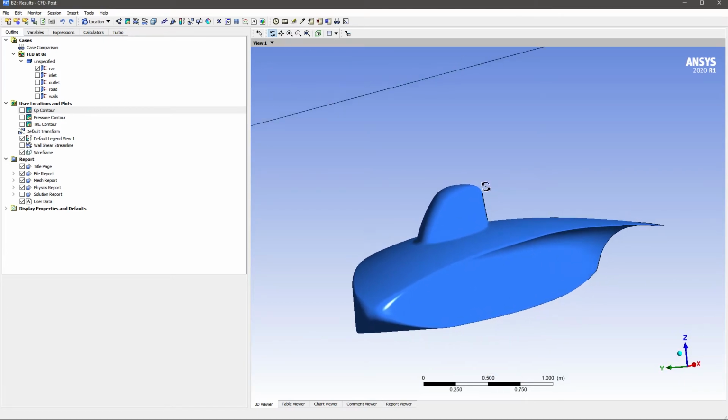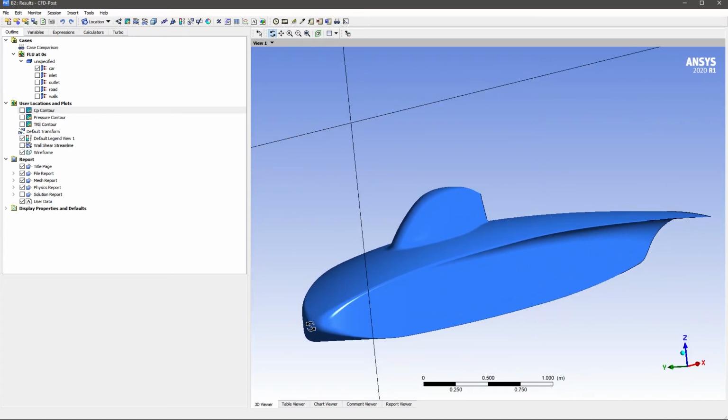Our goal is to create a line from which we will sample points, and along those points we will get the CP data. That CP data really helps us find adverse pressure gradient regions where we can maybe experience pressure drag or extra skin friction.